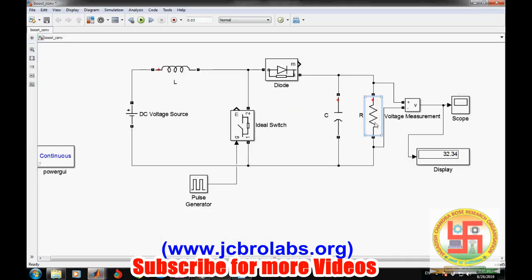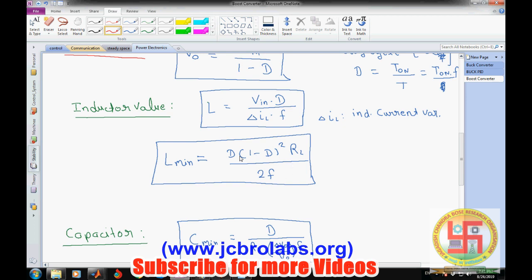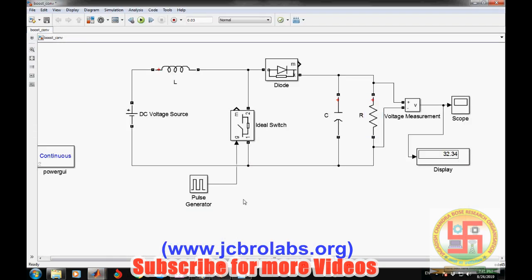We can make it again 30 volt by changing the duty cycle, because if we go through the formulas again, this value also depends on D. If L is changing and this L minimum is constant, the output can be changed by changing the value of D, because R and L also depend on the value of D. So there is a relation of the duty cycle in order to incorporate the change in the load resistance into the output voltage.